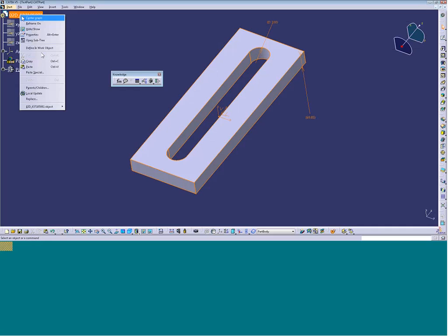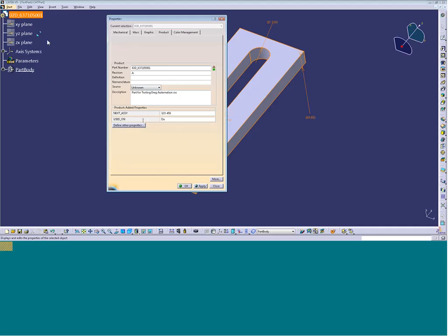So in this case, if we come in and take a look at the properties on this one, you can see that this already has some parameters in here. Some are missing. This is just some junk data in terms of part number and things of that nature. They have a distinct part numbering scheme, which has a 02D or some other 3-character designation followed by an underscore. And in this case, they wanted to parse that part number based on those rules. So this macro is pretty specific in that regard to the numbering scheme that's being used at ESD.